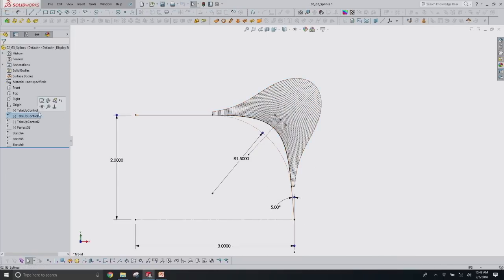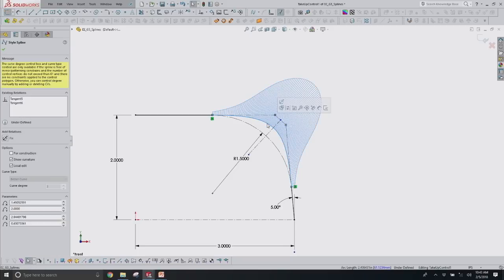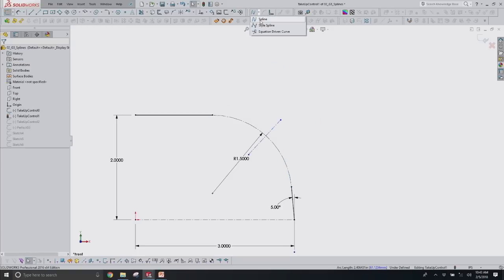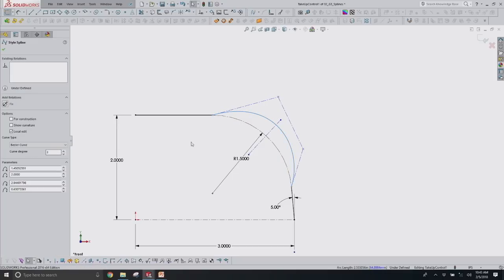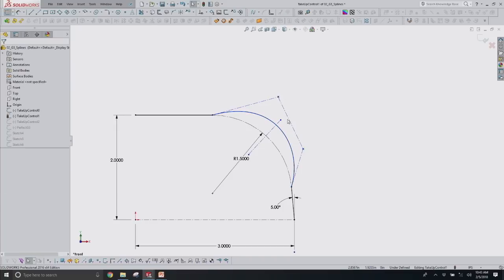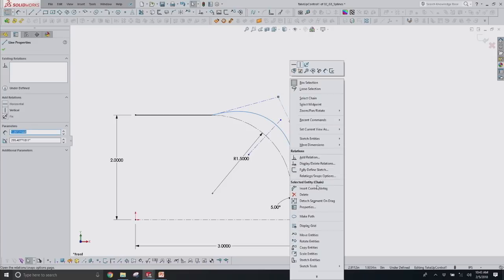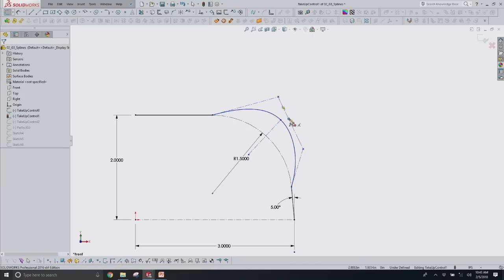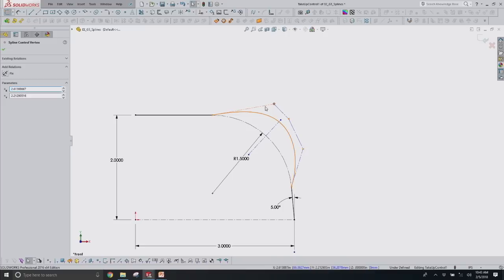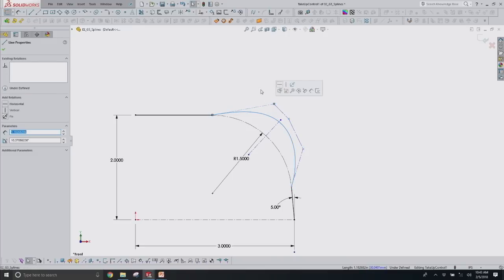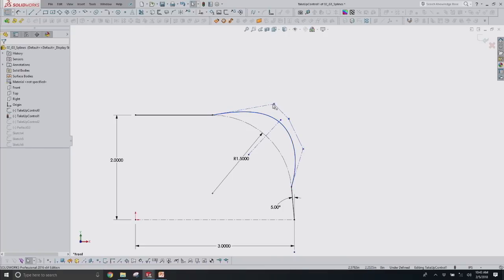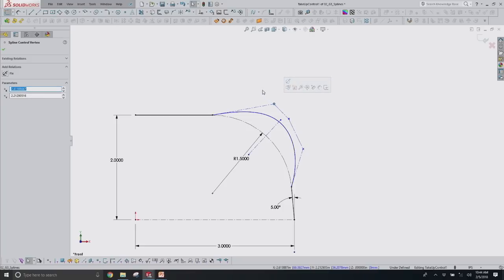So let's take that a step further, and I've got a style spline here, but we're going to redraw this one. I'm going to make sure that I have at least 4 control line segments. I can change that by changing the curve degree, or you can right-click and insert control vertex and just pick anywhere, and now you've got another. I don't know what these are technically called. I just call them control segments. The actual points are referred to as spline control vertex.